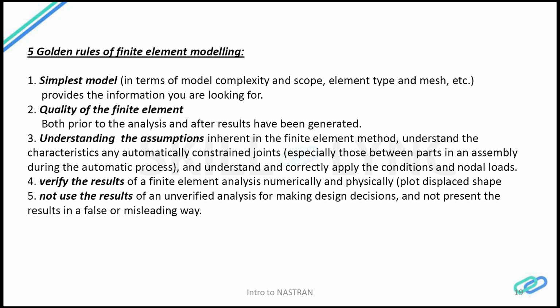You should understand the load paths, how the loads will be distributed within the model. In that way you can come up with a very nice and simple model, but at the same time mathematically very powerful, that would provide results that correlate with your hand calculations or any other justification.